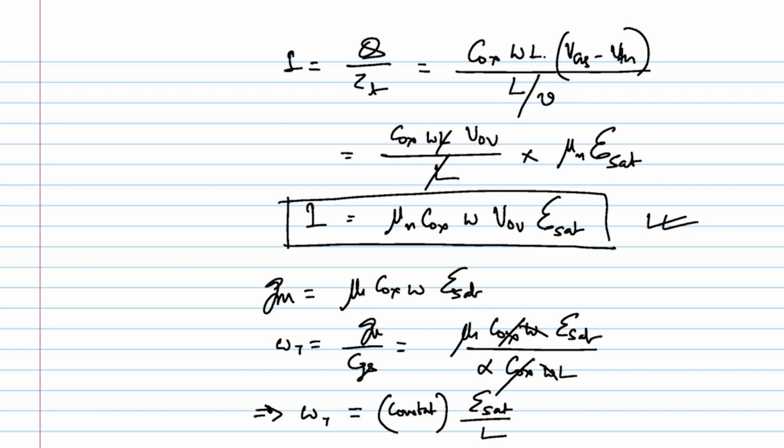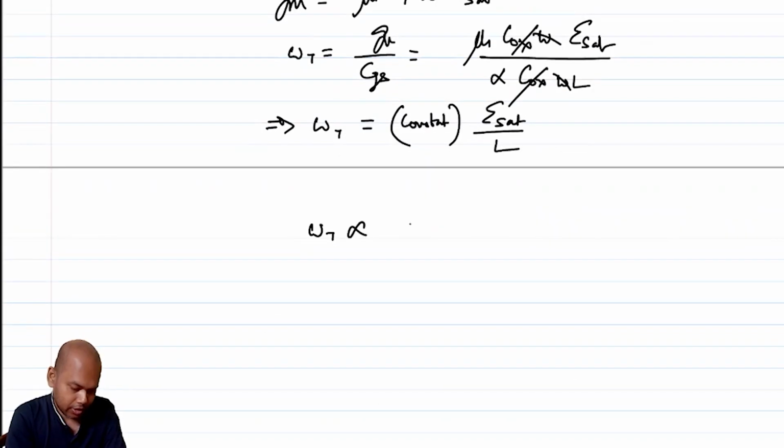So key thing again is omega T is inversely proportional to L and is independent of overdrive voltage.